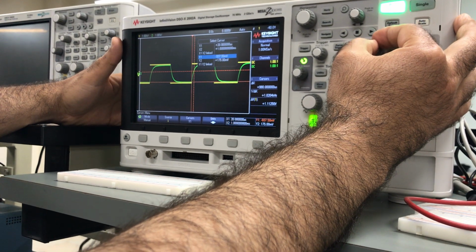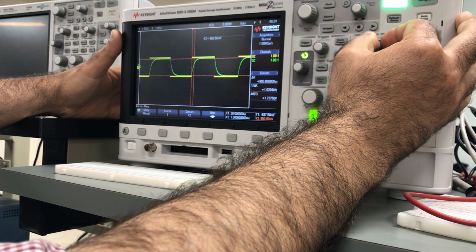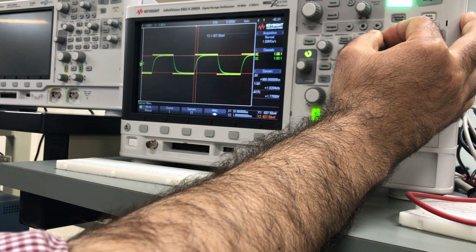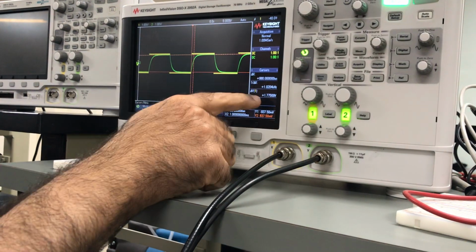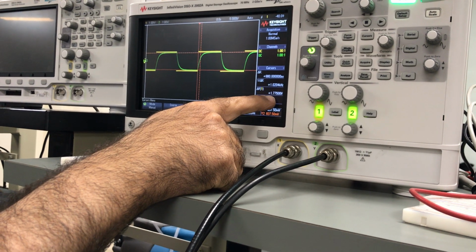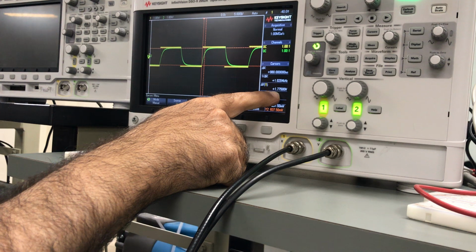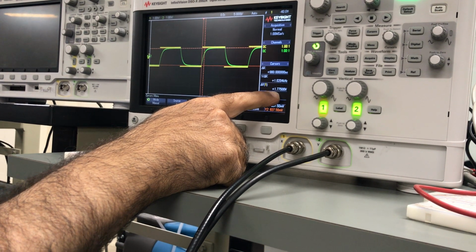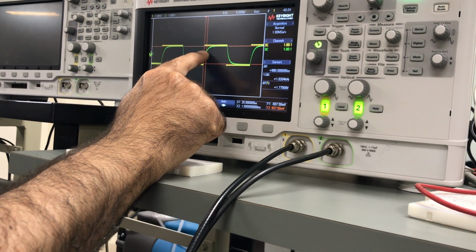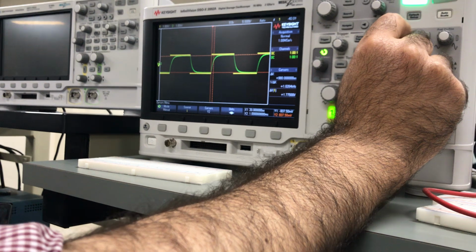Then I will use y2. I will move this guy. So delta y is approximately equal to, like what you are seeing, 1.78. I will multiply this value by 63.2% to give me delta y, which is 1.124. So I will move this line to go to 1.124 as a delta y.